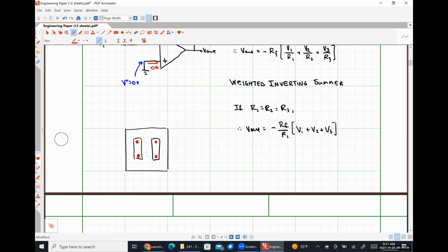So a nickel strain gauge uses a property called the piezo resistance of a material in order to cause a change in an output voltage. Piezo resistance is the change in resistance due to mechanical deformation. So when you stand on these nickel strain gauges, they deform, causing a slight change in their resistance.